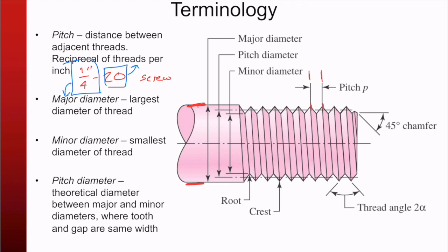So typically with English or American nuts and bolts, we refer to them by their major diameter and then their threads per inch. All right. Minor diameter, on the other hand, is down here. So this is the diameter that's the smallest, at the deepest point in the threads. What is the diameter there?